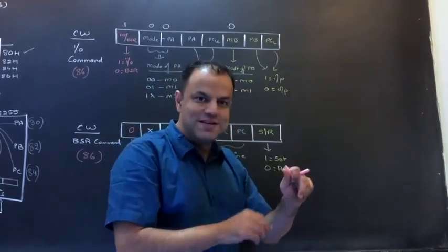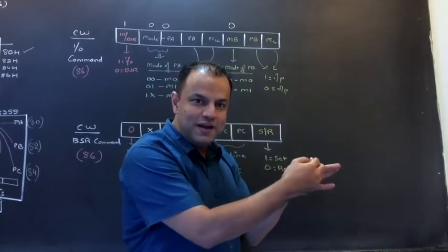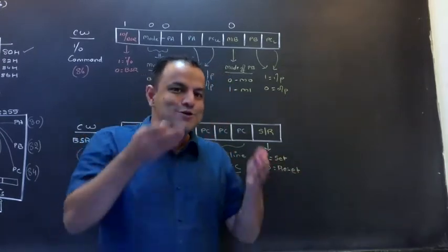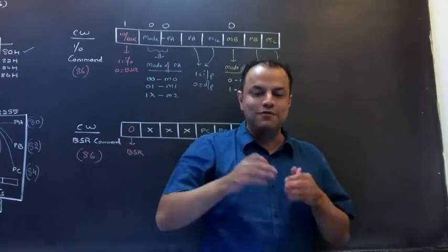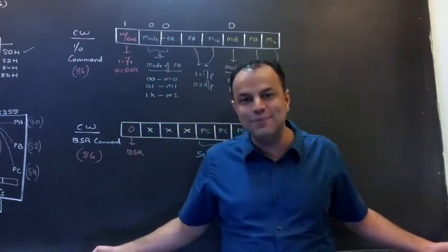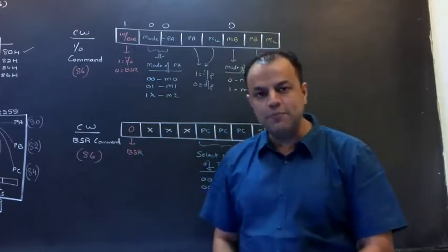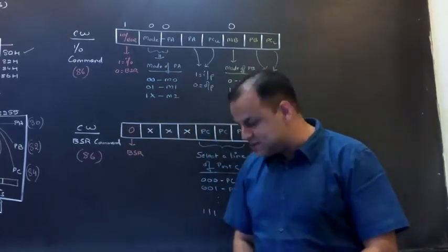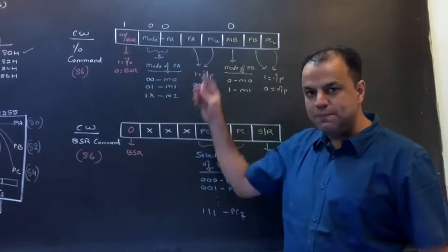Your latch has to be disabled so that the port becomes a free line so that somebody can send data to you. So for that you need to inform the port whether you intend to use it as an output port or as an input port. Please tell me, did you understand this? So you need to inform 8255 which port is input, which port is output. That you do individually port wise.